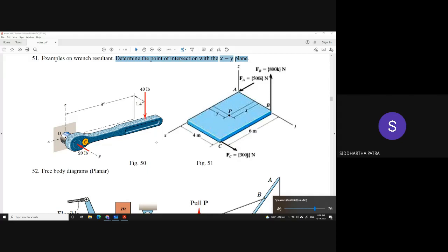No, the dot product should not be 0. You see, sir, no, let me finish. Don't think in terms of dot product and cross product. You see, the resultant force and the resultant moment must be along the same line, which basically means that the components of the resultant force and the resultant moment at P should be proportional, the Cartesian components.